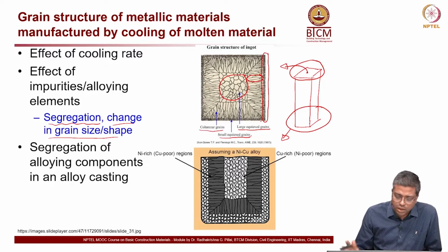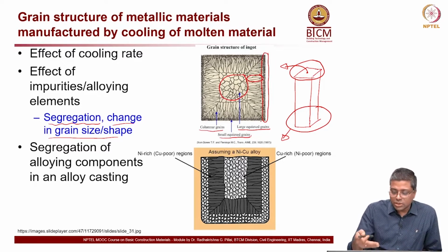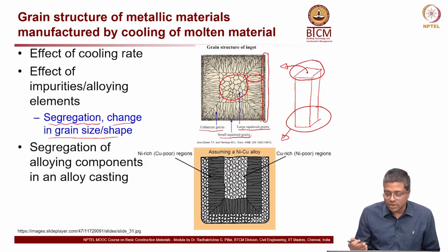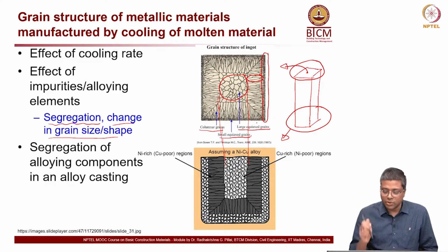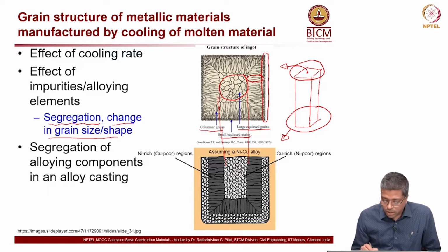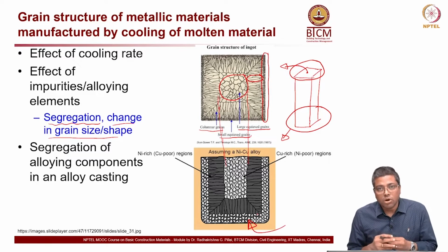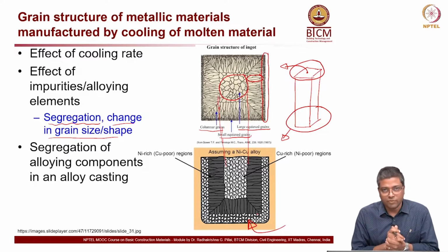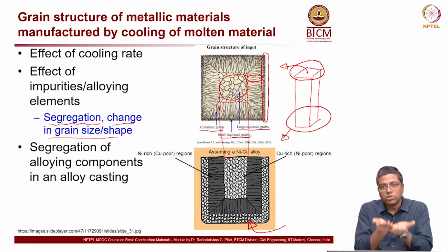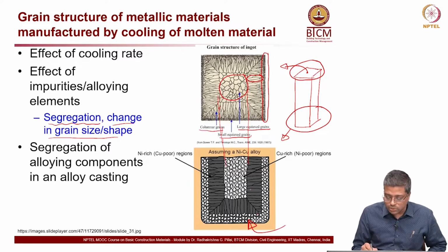Okay. Now, same thing, although these two images are from two different literature sources, I thought it is good to show them together. As you can see, this is what is happening. So, the side view, how it would look. Now, here the important thing is, at the bottom also you have similar grains, because if the material is a rod, it is cooling from all the surfaces, not only the circular surface, but also from the bottom surface it is cooling, and that is why you see this kind of